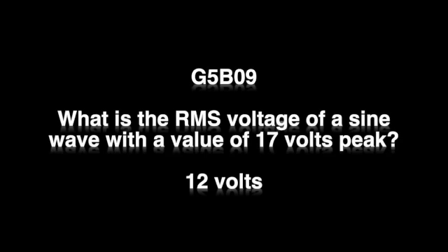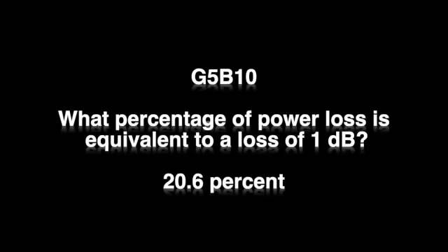G5B09. What is the RMS voltage of a sine wave with a value of 17 volts peak? 12 volts. G5B10. What percentage of power loss is equivalent to a loss of 1 decibel? 20.6%.